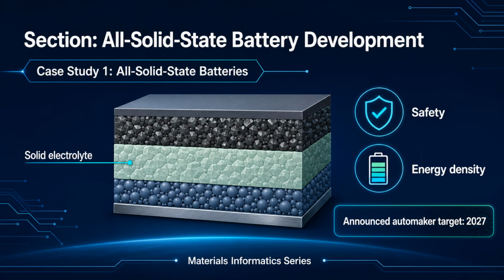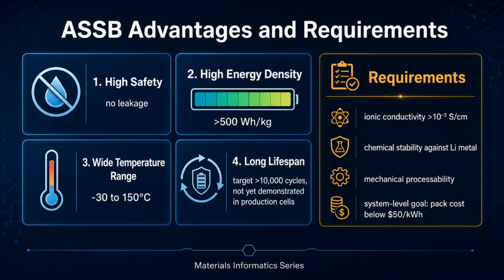Toyota and other major automakers are racing to commercialize these batteries by 2027. The key challenge is discovering solid electrolyte materials with the right combination of ionic conductivity, stability, and processability. All solid-state batteries offer compelling advantages. High safety comes from eliminating flammable liquid electrolytes.